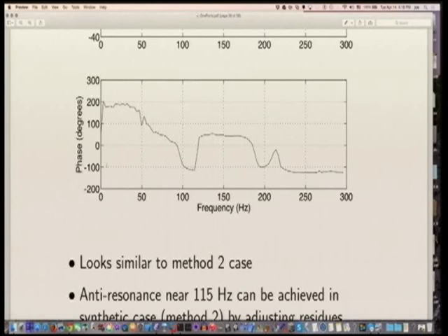It's also pushing the limits a little bit because this is 100. So you can imagine if you go up 10 here, it looks like it's pushing the boundaries. So this would be after the Helmholtz resonance, which is usually the most resonant mode in a guitar. In other words, when you knock on a guitar bridge, the last thing you hear usually is that Helmholtz resonance. That's the main air mode. That's the main breathing mode of the guitar body that's breathing out the air hole.